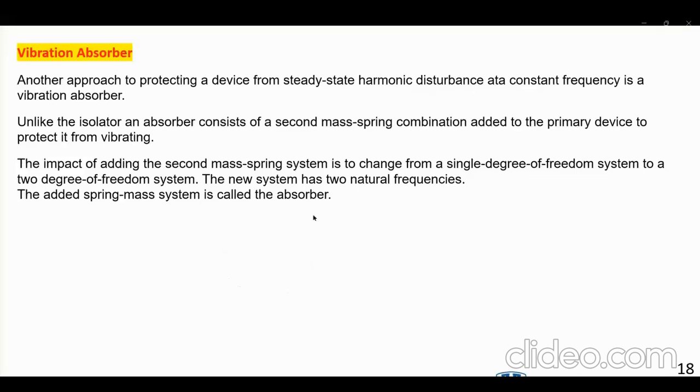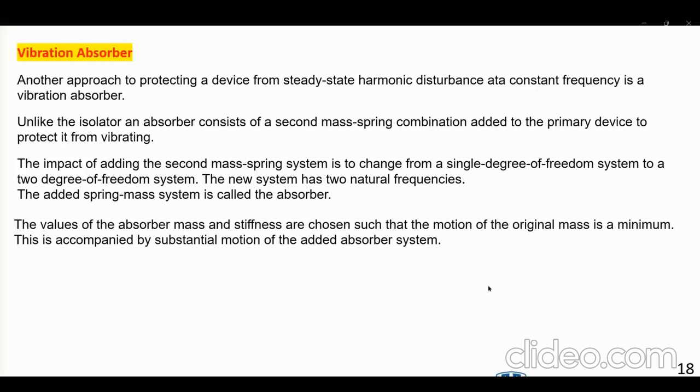Now, if you do this thing to analyze it, we may be going from a single degree of freedom into a 2 degree of freedom system, which has two natural frequencies, and obviously you have to stay away from them. We'll discuss this in the context of examples in a minute. Okay.